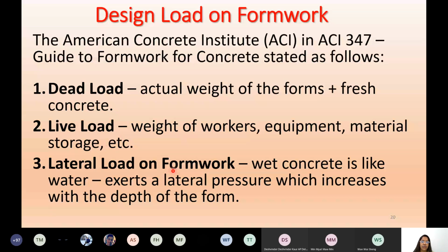Lateral load on formwork. These are the three types of loads which you need to design for during your formwork design and construction of formwork. Dead load is the actual weight of the form and fresh concrete. So dead weight is the self weight of the formwork plus the fresh concrete. Don't ask me why fresh concrete is coming in here, because it's also an element, right? So they put it as a dead weight. It is not moving. Live means something moving or changing.